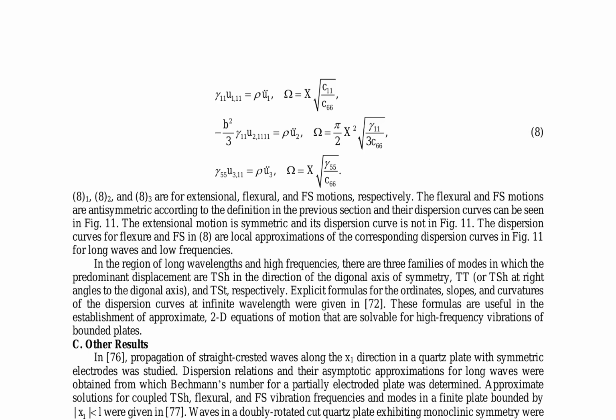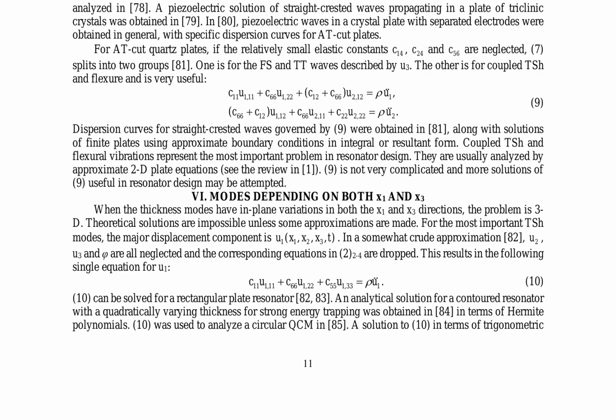The paper also reviews other results, including the propagation of straight-crested waves along the x1 direction in a quartz plate with symmetric electrodes, and the analysis of waves in a doubly rotated cut quartz plate exhibiting monoclinic symmetry. Additionally, piezoelectric solutions of straight-crested waves propagating in a plate of triclinic crystals are obtained, and dispersion curves for AT-cut